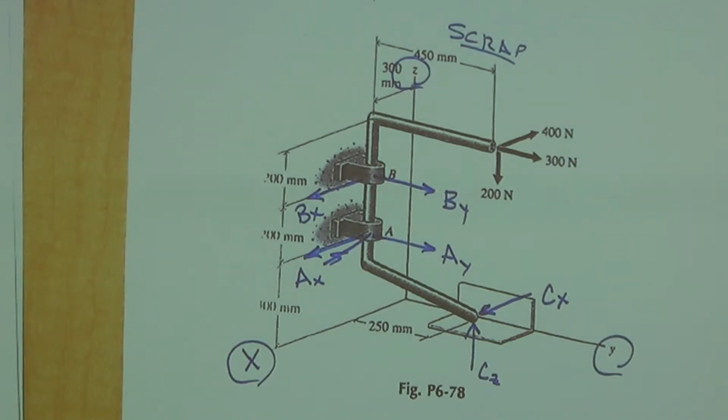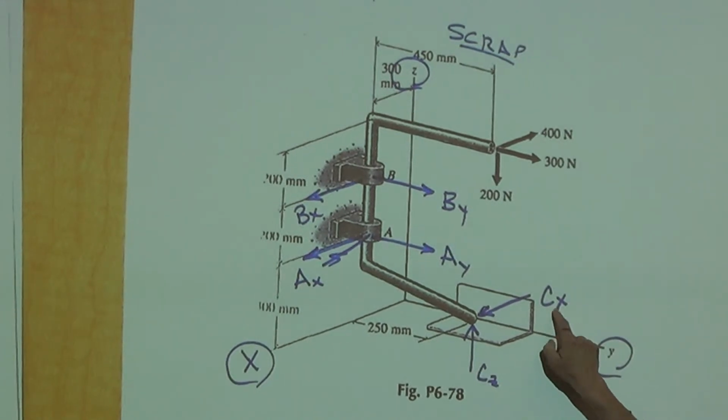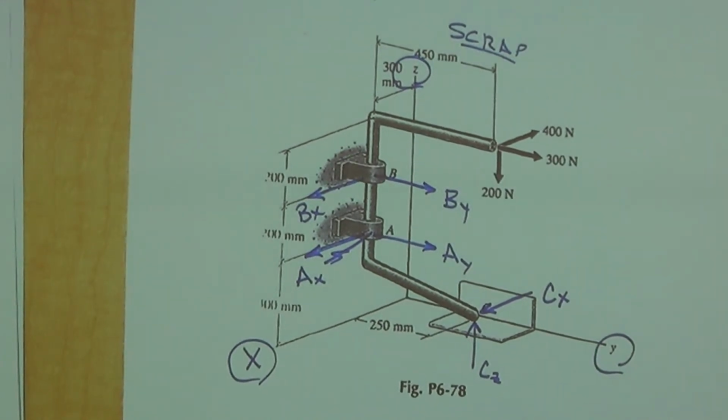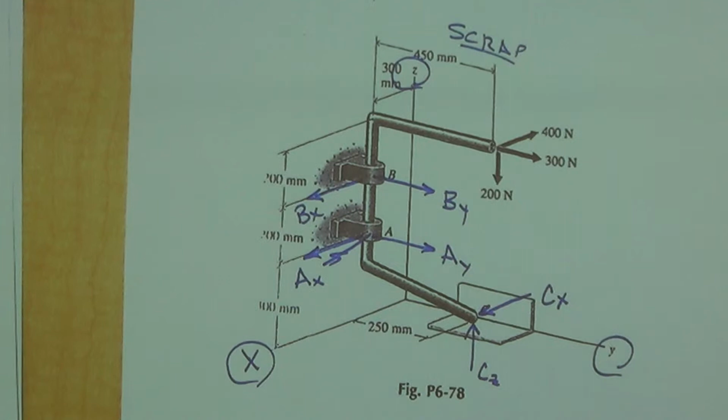Yeah, because I'm looking at the bar, right? I'm analyzing the bar, and the ground and the wall are pushing onto it. They're normal forces, right? If in the end, Enrique, I got a negative value for this or a negative value for this, what would it tell me? You did something wrong. Does everybody see that?